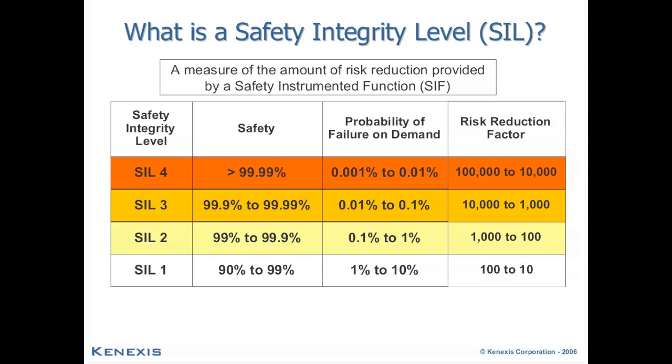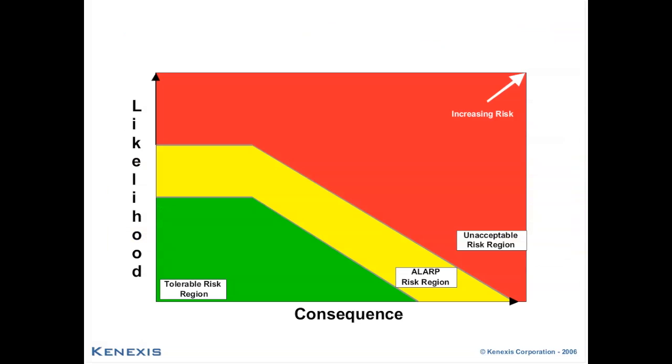In other systems, we may have more margin, we may have other protection layers, and we may require less of our safety system. In those cases, perhaps a SIL 2 or as low as a SIL 1 may be required. Those are the definitions of safety integrity level, and the process of specifying the correct safety integrity level varies company by company. There's no mandate in the standard to use a specific level of risk tolerance or even a specific method for selecting SILs, but most